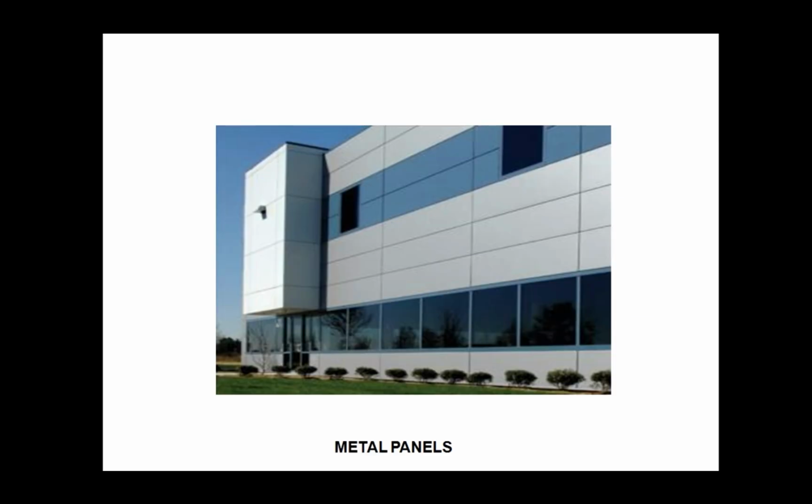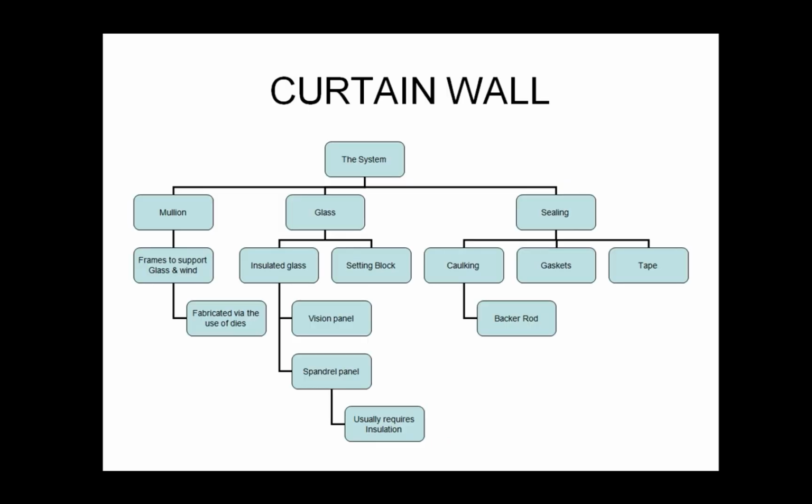Right, so metal panels are very typical construction. You see this a lot in office buildings, airports. It's usually a very quick construction because, again, the metal panels fasten directly to the structure. They're fairly light, and can be easily lifted and cherry-picked into place by smaller cranes. And then the more difficult and the more common for skyscraper-type construction is the curtain wall construction.